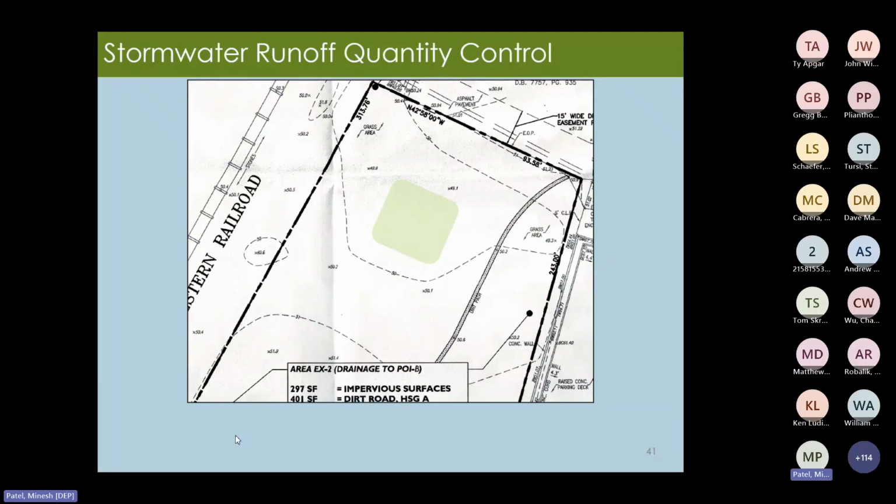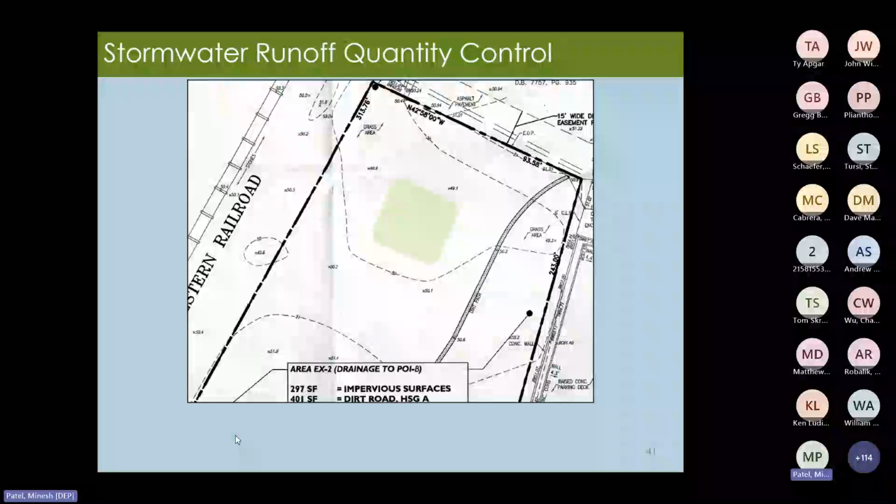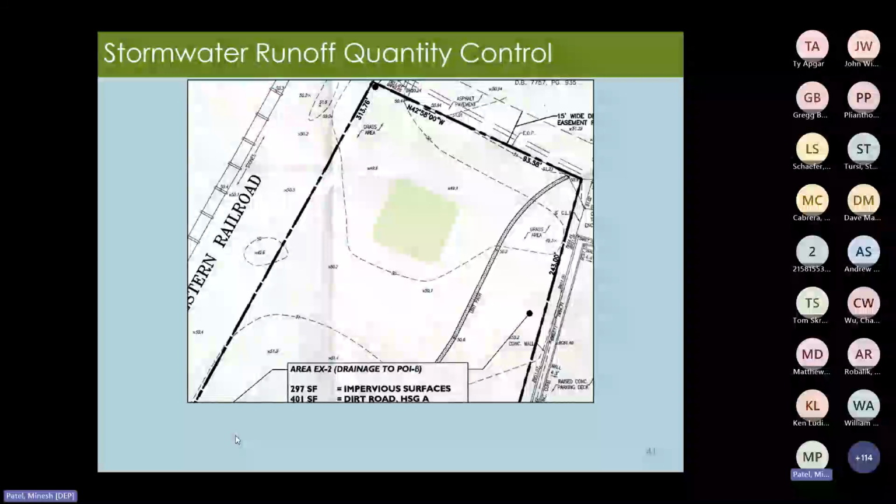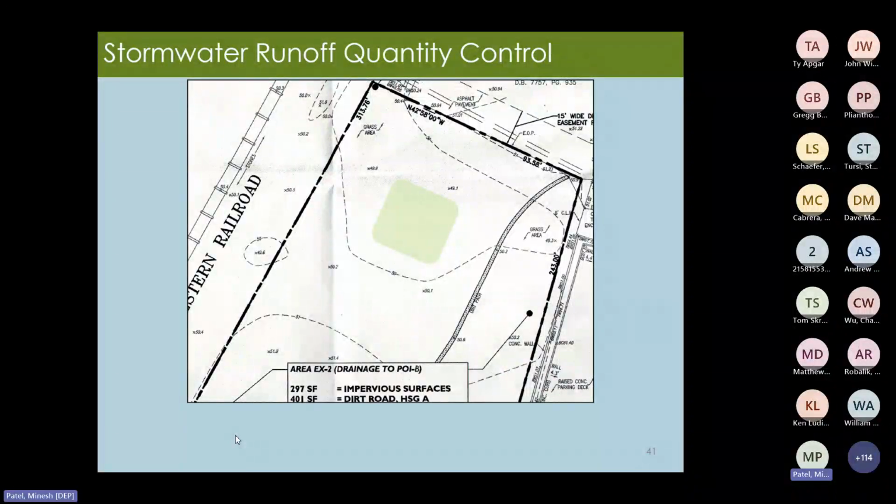So on the same example site that was shown before, there was a 6-inch deep ponded area within the shape that's depicted here. This was ignored, and the basin was made significantly larger than was needed. If there are any questions as to whether areas of ponding exist on site, and it cannot be determined from the photos of the site, you may just have to go there in person and see the actual site.